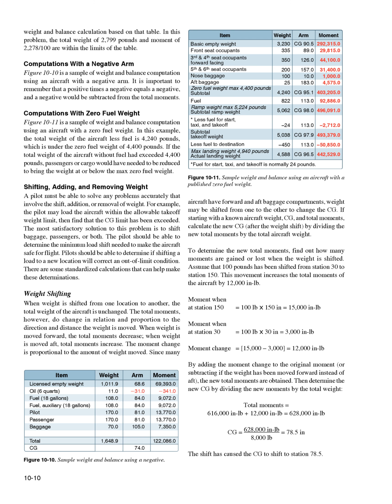Weight shifting: when weight is shifted from one location to another, the total weight of the aircraft is unchanged. The total moments, however, do change in relation and proportion to the direction and distance the weight is moved. When weight is moved forward, the total moments decrease. When weight is moved aft, total moments increase. The moment change is proportional to the amount of weight moved.